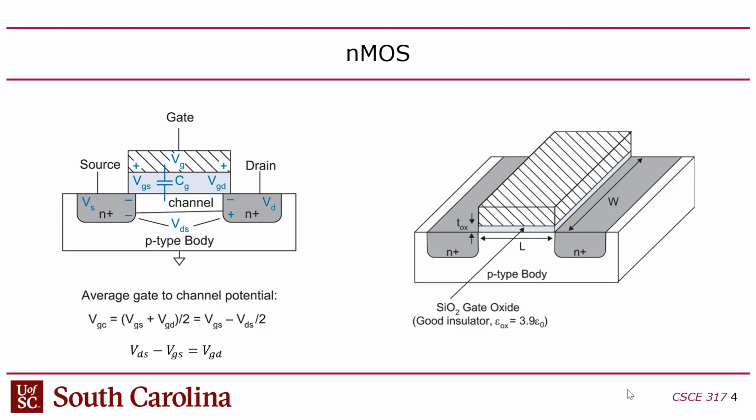So if you need a transistor that has more oomph, more power, then you increase W, right? Now, actually, you don't increase W, because the way you lay out chips, you have a limited space for these things. So what you end up doing is you increase the width by making multiple parallel transistors. You can make the width bigger virtually by having multiple parallel transistors that are all contributing charge carriers at the same time. You get more power out of the transistor, and thus it'll switch faster for a larger load.